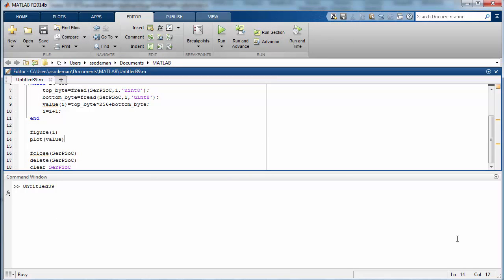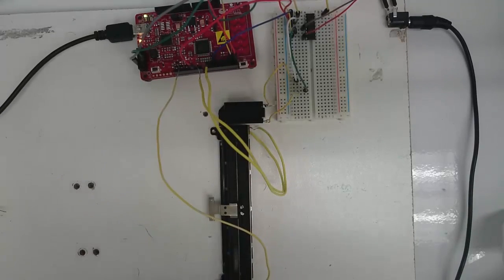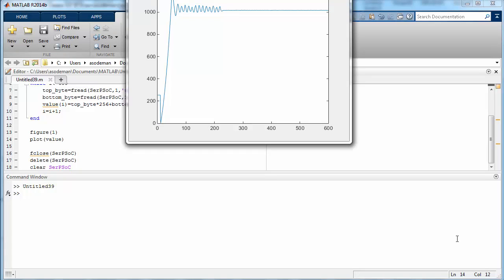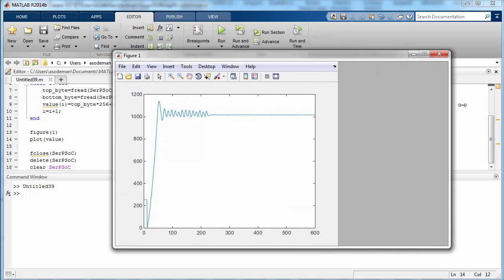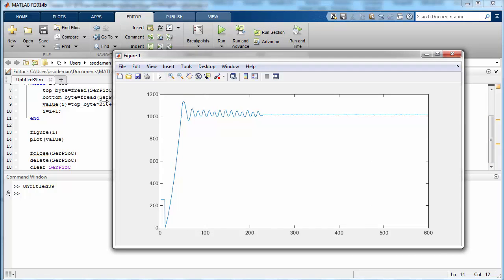And then as soon as you've got it running, run the PSOC code by clicking Program in PSOC Creator. So you see what happened was my slider shot to the center and it was a little unstable. It vibrated back and forth, and at the same time the MATLAB popped up a plot, our figure window.